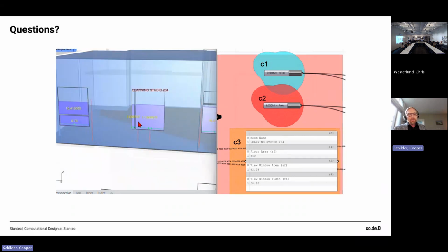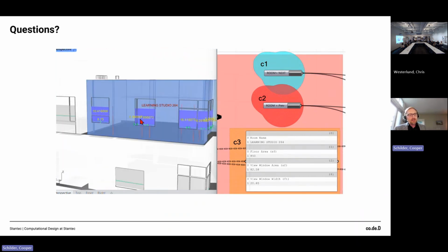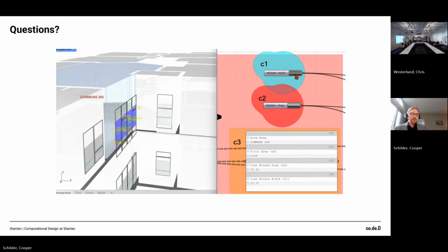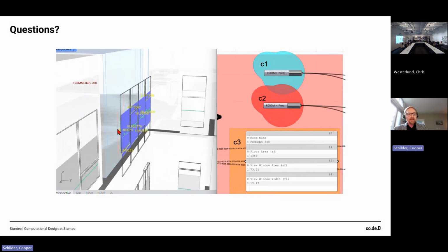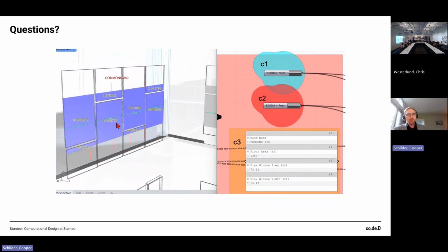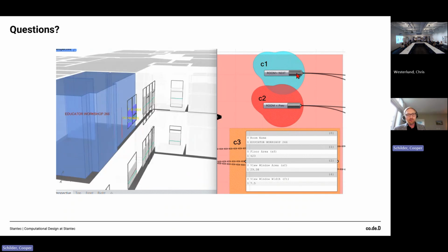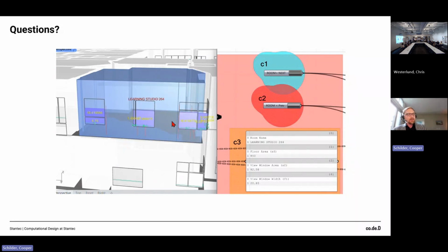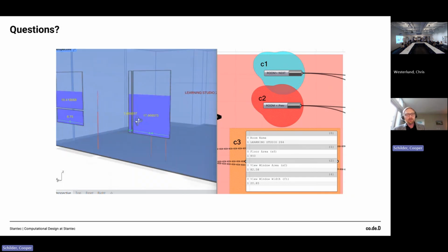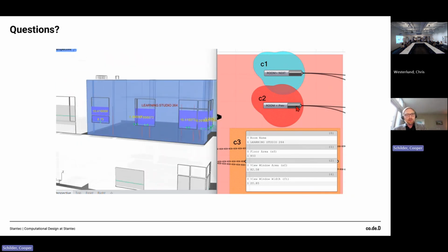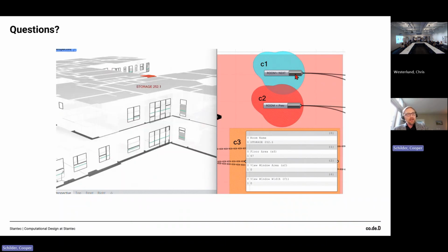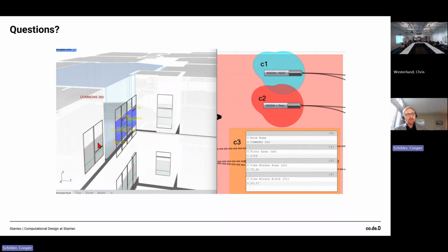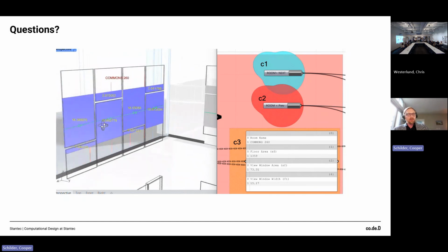Yeah, so Dynamo, from my experience, the geometric capabilities are somewhat limited. It runs much slower. Rhino and Grasshopper in this case, I think, give us the capability to run this at a much faster speed and dive into the data a little closer, since the Rhino window allows for more graphical display than Dynamo. For the most part, I don't use Dynamo as much for anything related to geometry or even data analytics, and use Dynamo mostly for sheet creation and documentation efforts.